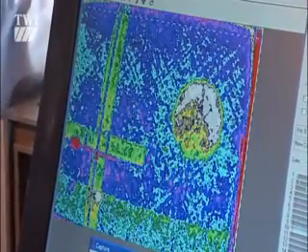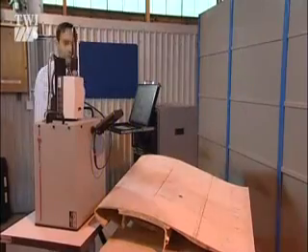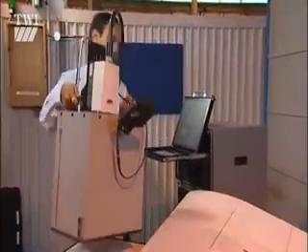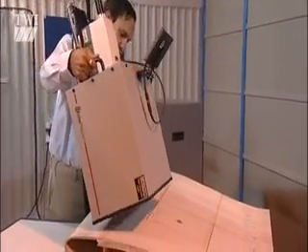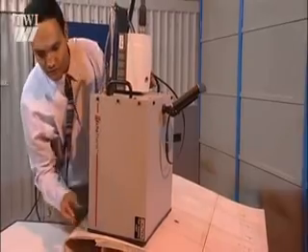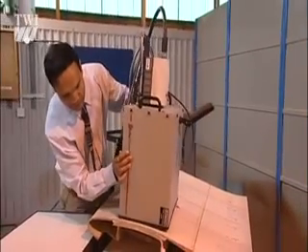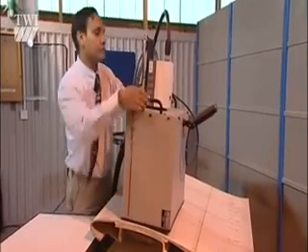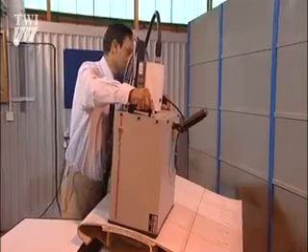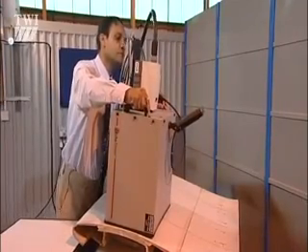Thermography is a remote technique for use in most areas of plant, but is particularly suited to equipment operating at elevated temperatures. Active thermography, where heat is applied directly to the component, is used for inspection of low conductivity materials like composites,